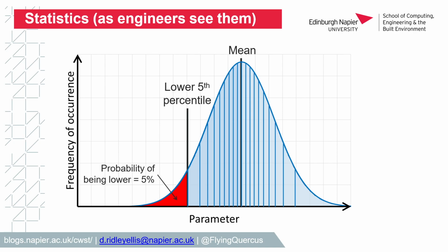Some of the bits of wood will not be possible to grade and will have to be rejected because of the wane or the cupping is too much, the disfigurements too much, and it's not possible to physically grade them, so they'll be rejected. They'll be rejected by hand. But the rest of the wood, you will have a standard deviation curve, something like that, a bell curve. There will be the mean, which is the average.